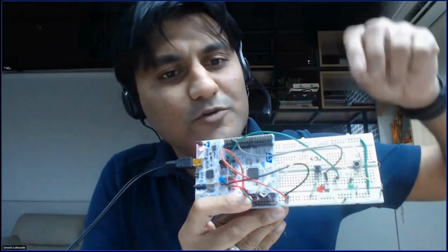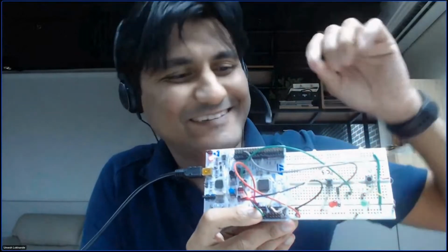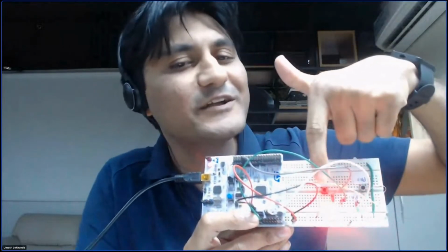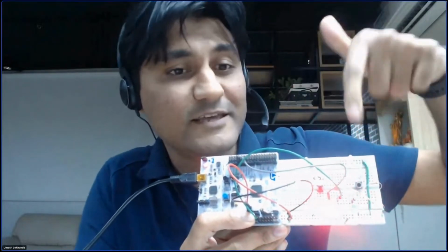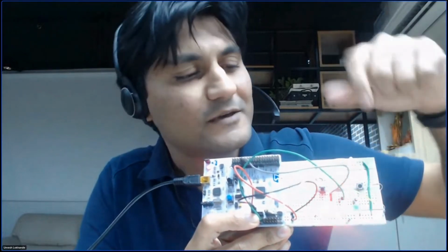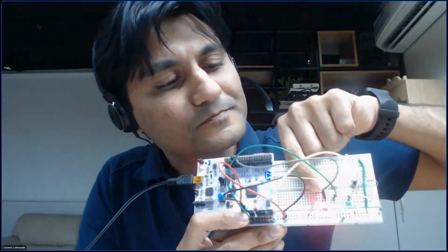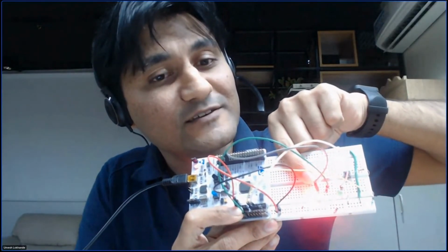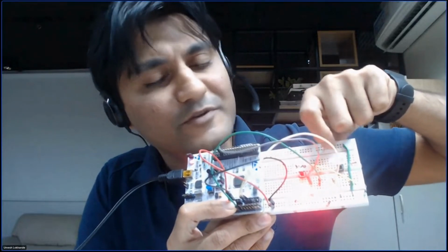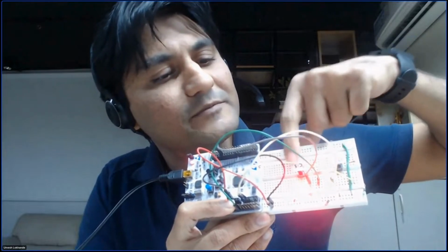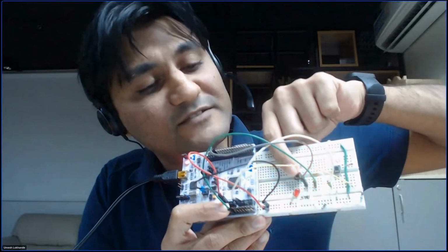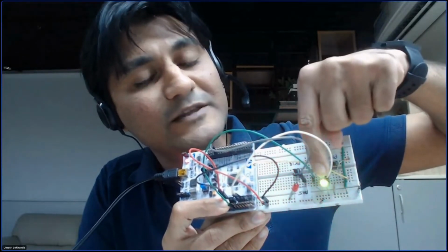So when I press both buttons, believe me, I press both buttons. You see the high priority interrupt, because it has the highest priority, is executing, so the red LED is blinking. But even though I pressed the first button as well, it didn't blink the green LED. But the moment I stop the high priority interrupt, look at this. Oh, when I stop, I think it didn't press, but you can see it's blinking because this is stopped. So when I stop the high priority interrupt, you look at this blinking, right?